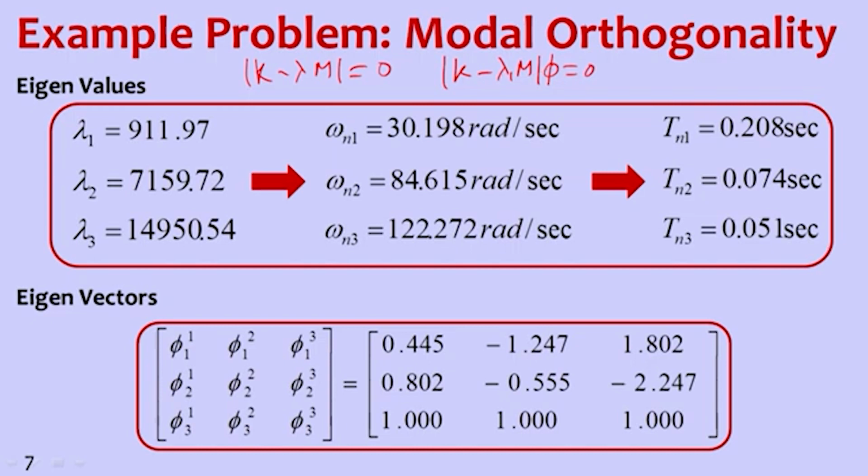So when we solve this one, we get the phi value corresponding to lambda 1, so that is phi 1. Like that, first mode phi 1, first level, second level, third level. So phi 1, phi 1, phi 1, phi 2, phi 2, phi 2 and phi 3, phi 3, phi 3. This is mode 1, this is mode 2 and this is mode 3. So values of mode 1, mode 2, mode 3 are known.